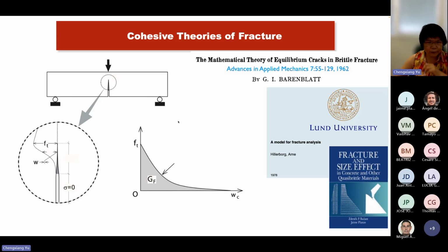In comparison with linear elastic fracture mechanics, in the cohesive theory of fracture you can see from the shaded area of the sigma versus opening curve that after the fracture has started, it still has some resistance and it can transmit stresses between two crack lips.